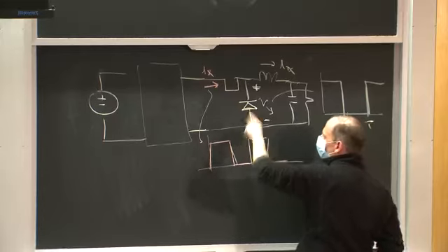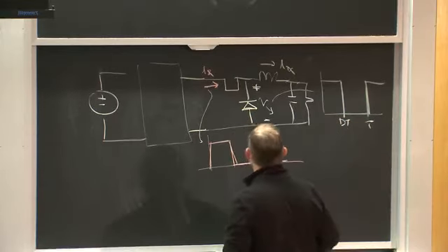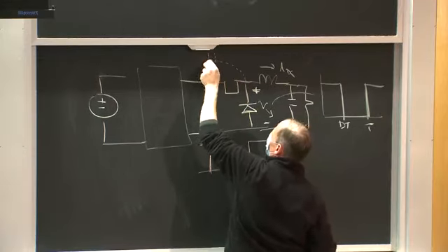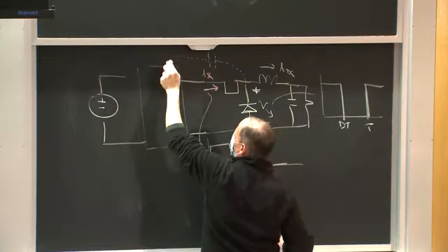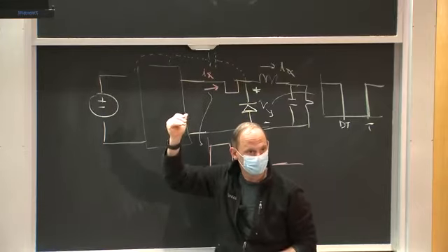Now that doesn't appear specifically out at the converter, but remember, maybe I might have some parasitic capacitance coming back here and either into my filter somewhere or towards my input somewhere. So basically this very sharp voltage sort of injects currents back. And that can appear as noise either within my circuit or at the input or output somewhere, okay?